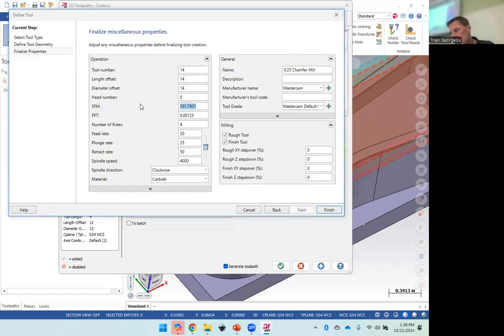It's going to run a surface speed. We're trying to max it out here, 650. It's almost like 10,000 RPM, right? It's a 4 flute and it's going to run a 2 thou chip load. So I go up to 80. Sound good? 80, and then we'll do a 40 plunge for now.